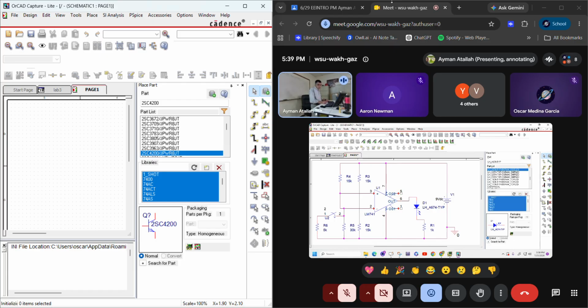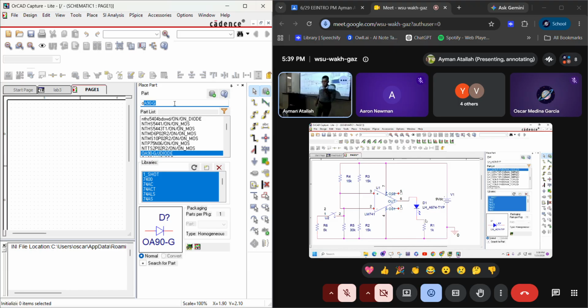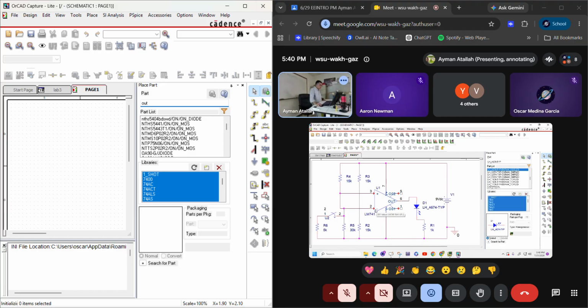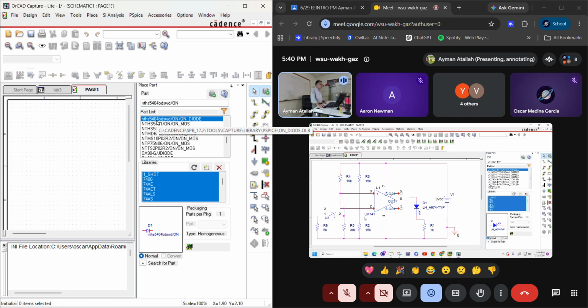You also have it connected right there on top of R5. I don't know, in the picture it doesn't show that. Which one? R5. R5 is 30K. You have it connected from there to the... I connected this here. It's this connection here from here to this here. Oh, right. Yeah, I connect both two inputs to the same point. This is my mistake.